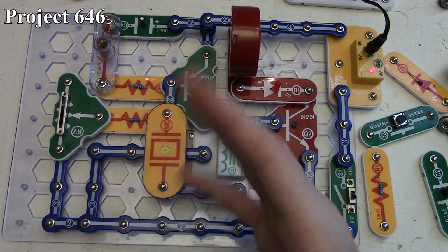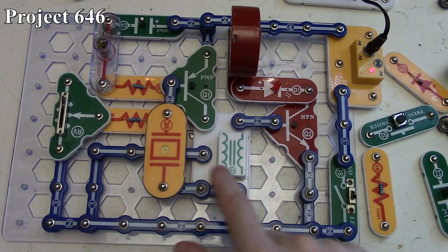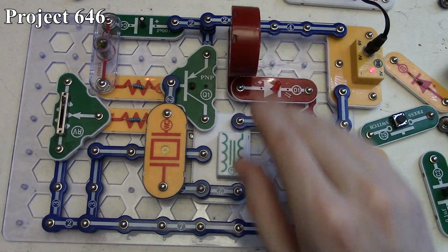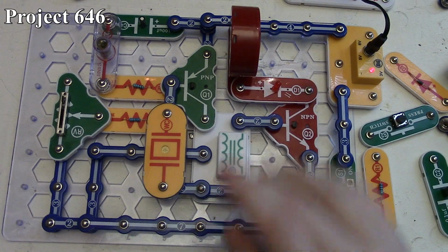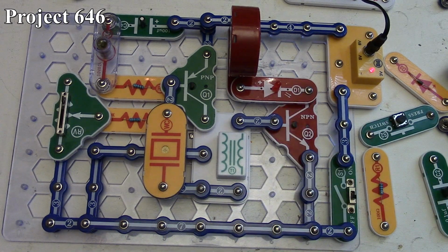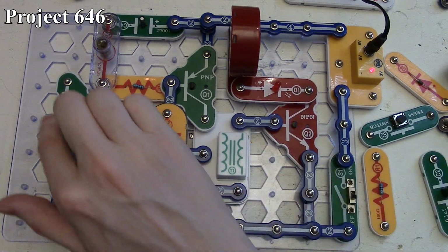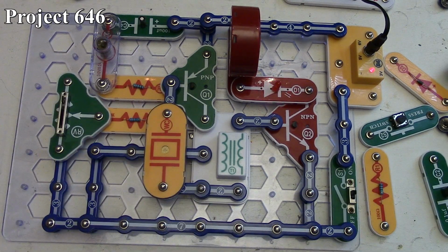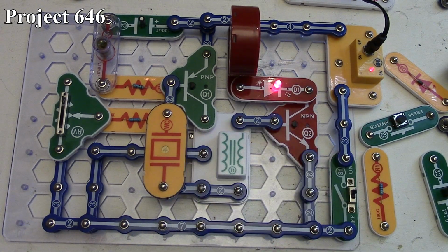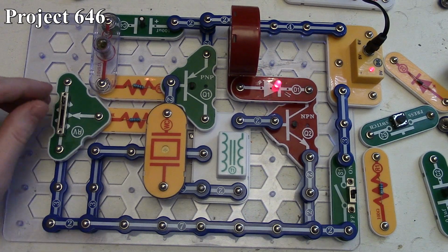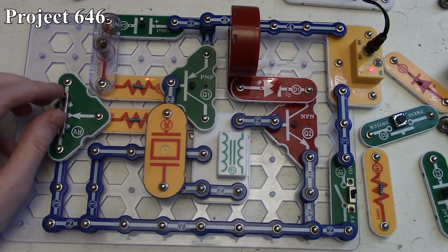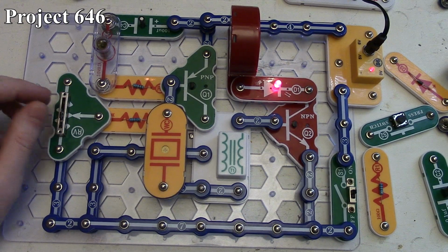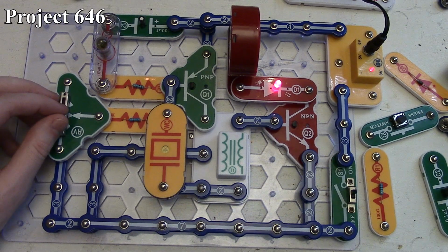So as the circuit oscillates, it creates an AC signal, which then of course will turn our NPN transistor on and off, and we'll hear the oscillation both through our speaker and visually see it through our red LED there. So we set our variable resistor all the way to the top, and when we turn the circuit on there, you can see our LED is pulsing, and you can hear it also coming out the speaker there. And if we adjust the resistance, we of course change the frequency of the oscillation, making it oscillate faster and faster.